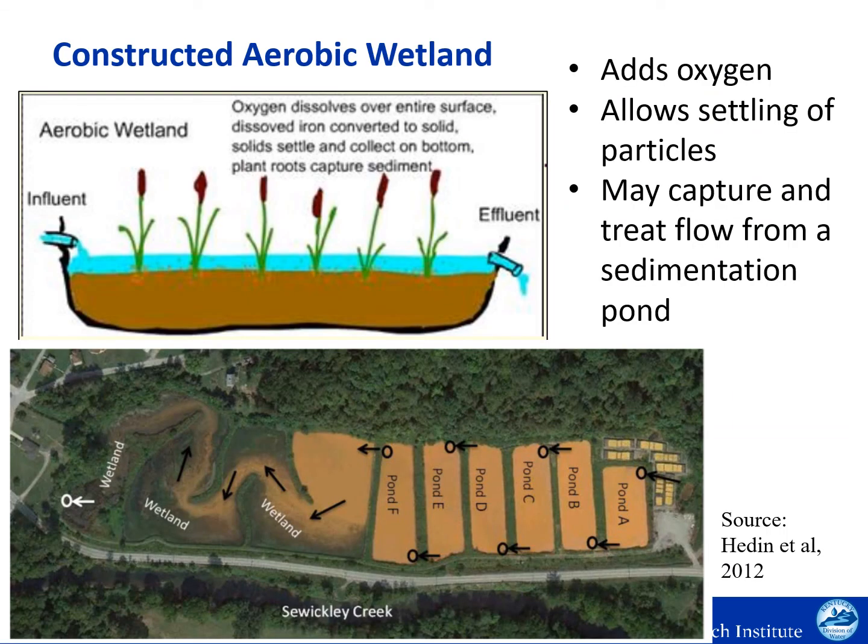In examining these passive treatment systems, we'll begin with the constructed aerobic wetland. Artificial wetlands are utilized to aerate and settle metals in mine drainage. The microbes in a wetland system can help further remove heavy metals, fixing them in the underlying soils in an insoluble state. They are typically recommended in conjunction with other mine drainage treatment practices. For example, they can become long-term passive treatment installations that receive pre-treated water from settling ponds. Sludge may need to be periodically dredged and removed from these wetlands.